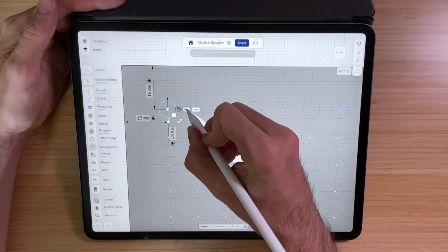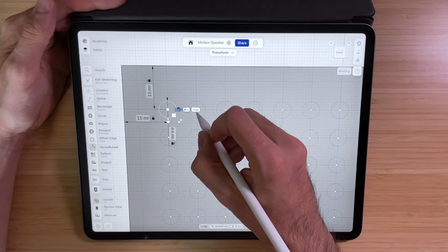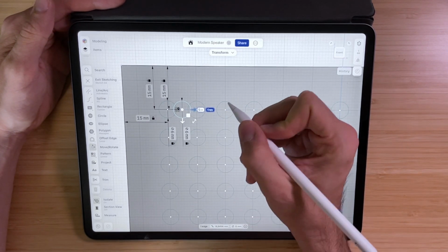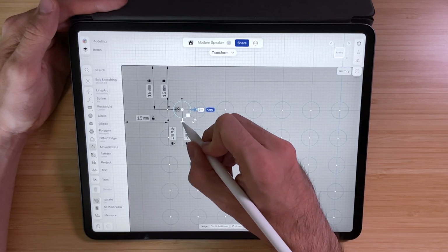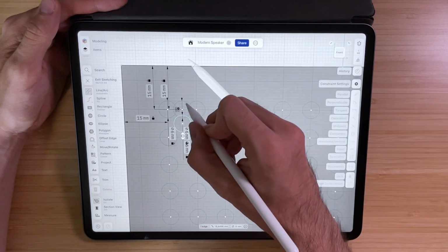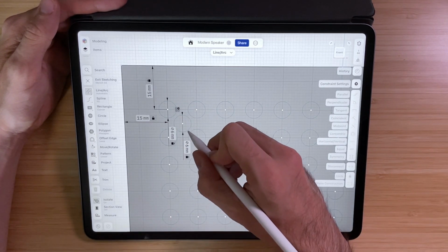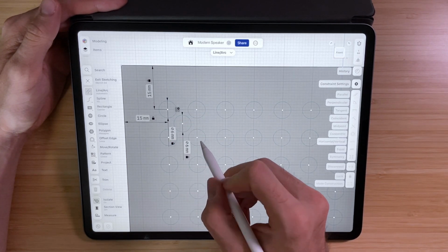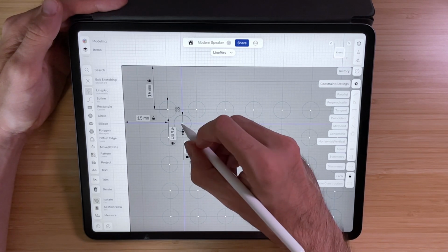If I just want to move, it tells us can't move it because it is constrained and locked. So that means we need to highlight copy in order to create a new circle, a copy of that first one. And we'll actually create 2. So basically 1 to the right and 1 to the bottom. And our first copy, we can actually delete. We don't need that one. So now we have our circle in this area, in this free space. So it is a new circle and it has the 6 millimeter diameter, but it still can move.